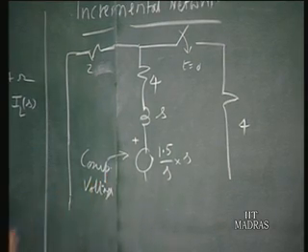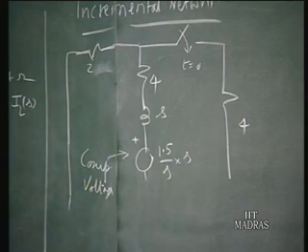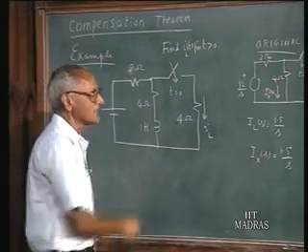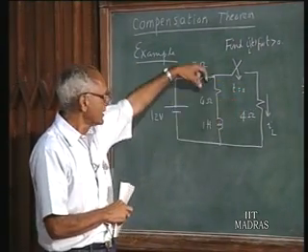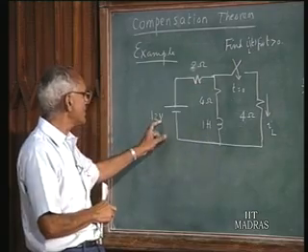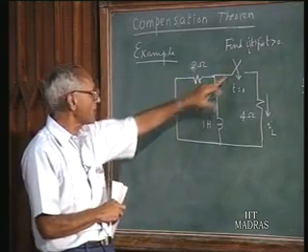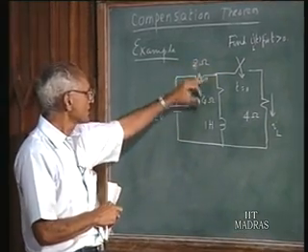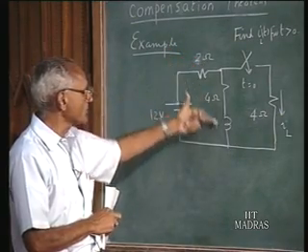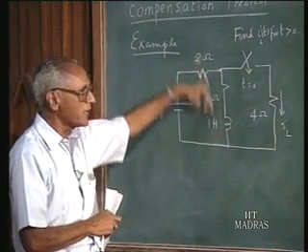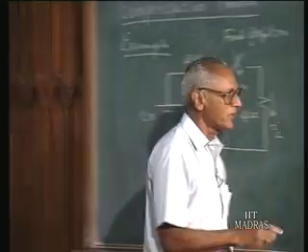Right. But that is not all, because this inductance here in the network also has an initial current. Before the switch was closed, the inductance is carrying a current, and what is the current? When the switch is open, 12 volts drives a current of 2 amperes through these 2 ohms and 4 ohms in series. Therefore, a 2 ampere current was flowing through that. Therefore, we have